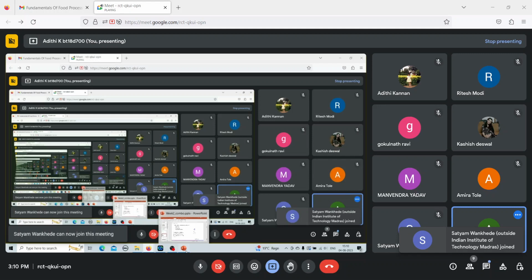The Maxwell model was the one in series, the Kelvin model was the one in parallel, and the Burger model is the combination of the Kelvin and Maxwell models. The Kelvin model does show excellent retardation, but that is not the case in many foods. It models a lot of viscoelastic fluids, but when it comes to food, it lacks precision. So the Burger model is proposed, a combination of Kelvin and Maxwell. You will have both parallel and series, and that is suitable for biological materials. So the answer is option D.